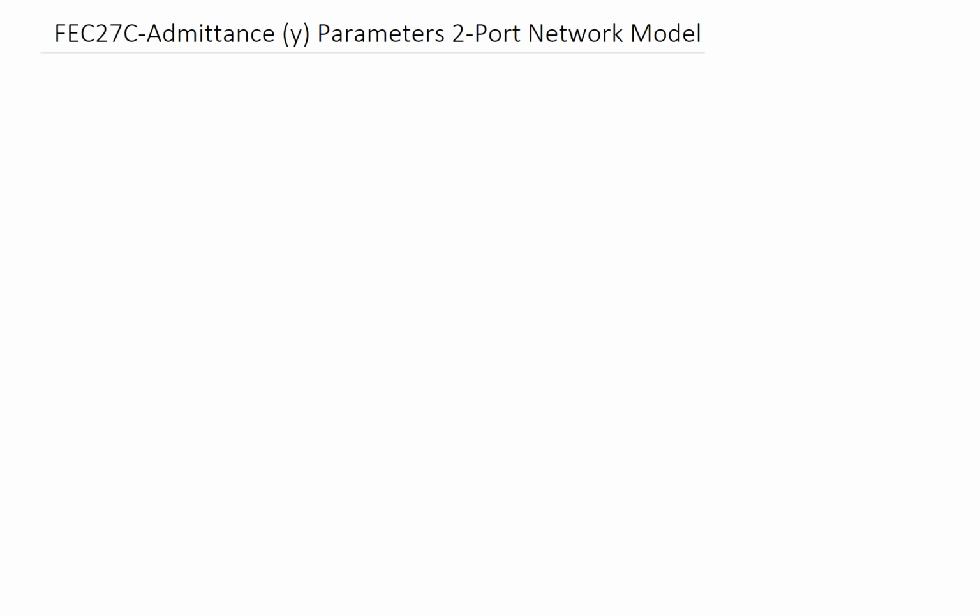In this video of fundamentals of electrical circuits, we're going to cover admittance, or 1 over Z, or Y parameters. As we've discussed in the earlier videos on this topic, we will be focusing on writing parameters that completely describe two-port systems. So Y parameters, as the name implies, describe any circuit that fits the two-port definition in terms of 4 parameters that are collectively called Y parameters.